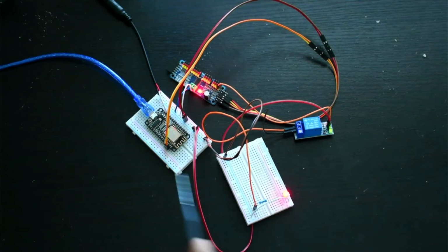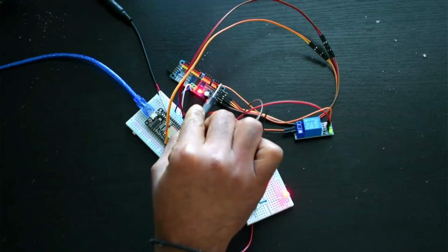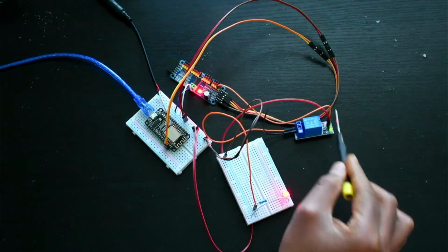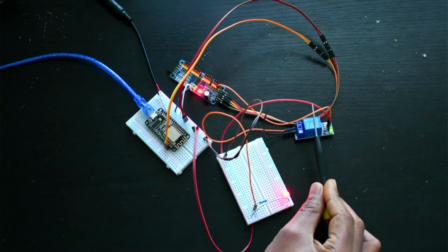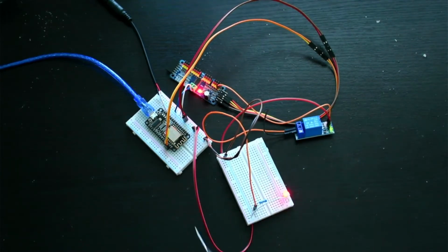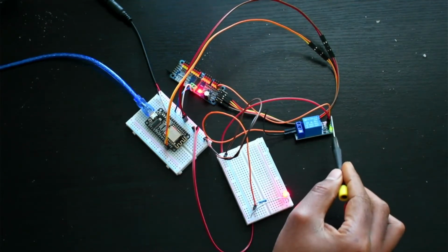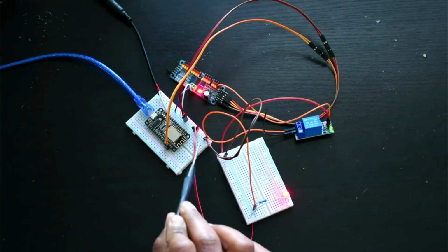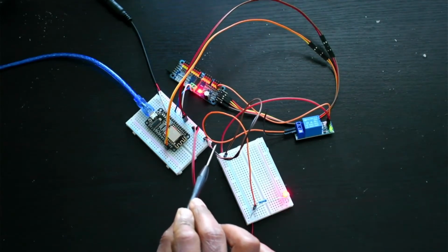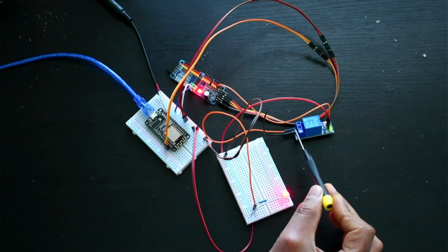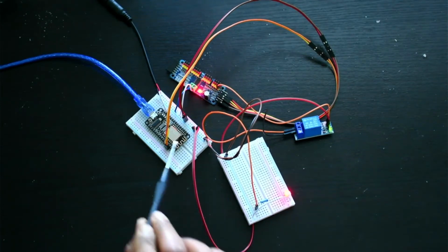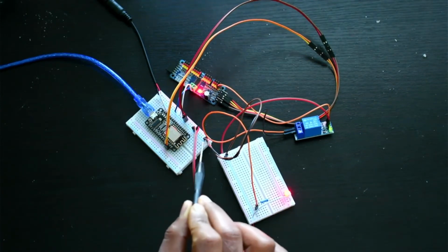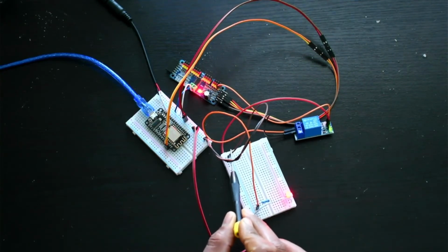And here you can see from the PWM pin, this orange is taking an input signal to the relay switch, and to control the relay switch, this brown and red wire is taking 5-volt external power supply from this breadboard here. This is going like this and it's going here. And then you can see this black and brown wire. So the black wire is going to the central part of the relay switch, and this orange wire is taking back the power to this breadboard here, and this brown is carrying the ground to this breadboard here.